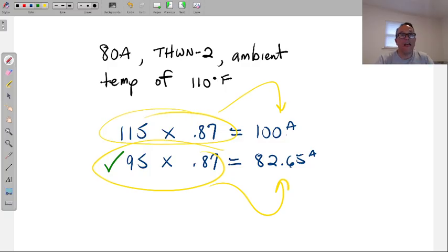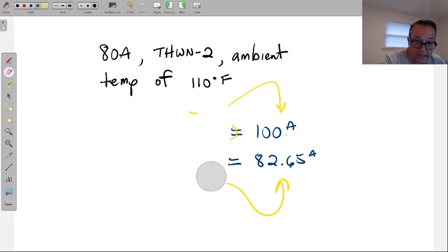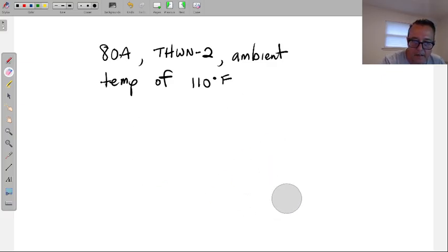The other thing that we were able to do, we were able to go, well, 80 is the starting amperage. Let me go right above 80, 95, 115, and let me start to work my math out. However, I'm going to change things a little bit. We're going to keep this 80. The only thing I'm going to change here is the temperature. All right, I'm going to make this now crazy hot. Let's go with a high temperature. It still has to exist in the table, so that's why I have to look at this table. Let's go with 152 degrees Fahrenheit.